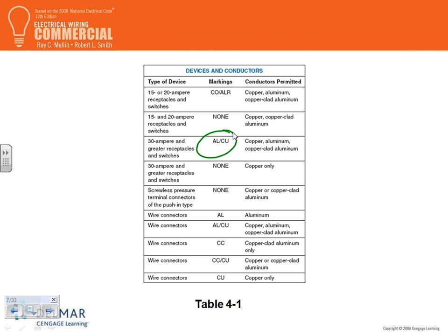You can't mix the two together, right? We can mix them together, two feeders, but we can bring either or. The lugs are rated for either or. So that's basically it, and this becomes an issue only for feeders, or major branch circuits, going all the way to like 100 amp or more.